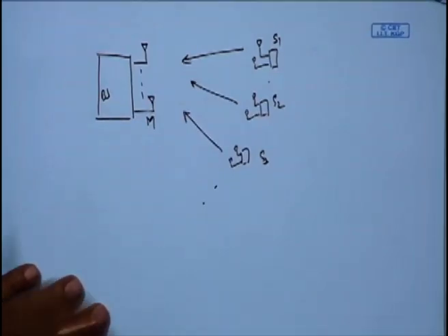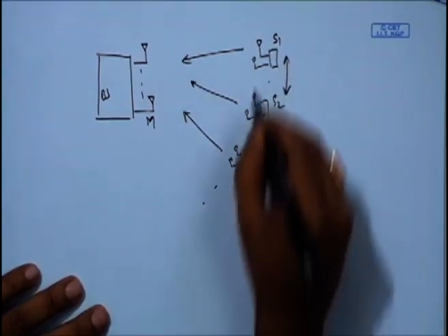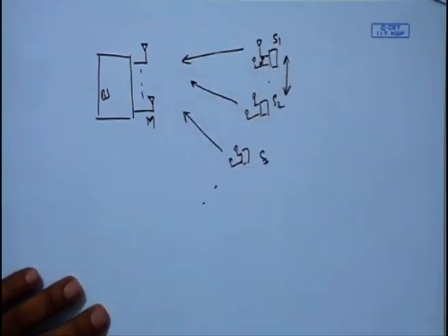One can also understand that in this situation the users are usually far apart compared to the separation of the antennas. And what we have studied is that as the antenna distance becomes smaller and smaller, correlation increases between the antennas, whereas when the antenna separation increases, correlation decreases.